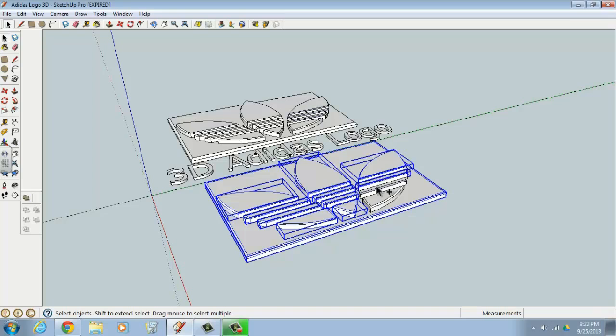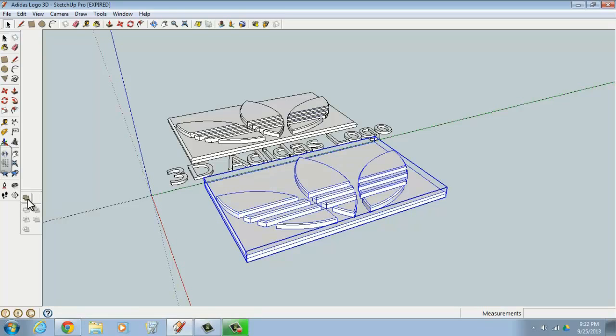And the only tool that's available in the free version is this right here. It's going to combine all selected solids into a single solid and remove any interior pieces. So if you click on that button, you can see that they're now not individual entities. Anytime I click on something, whether it's the base or part of the leaf, it treats it like one solid model.